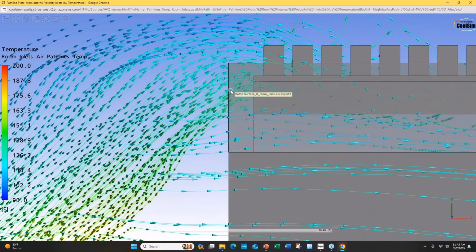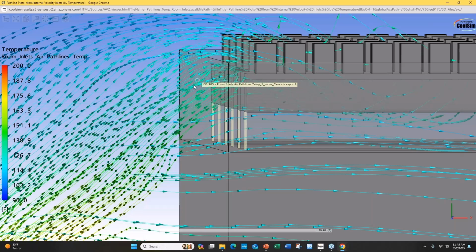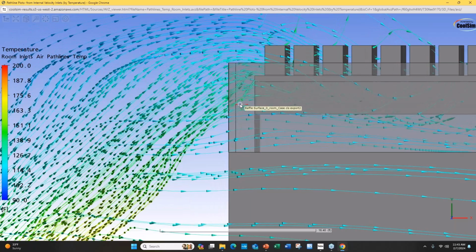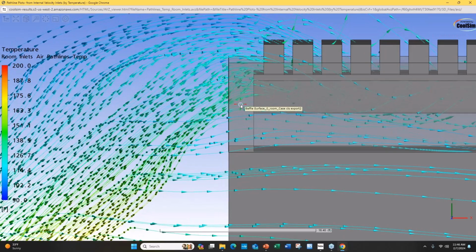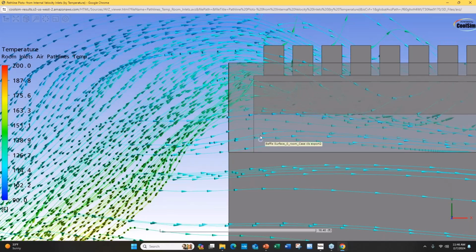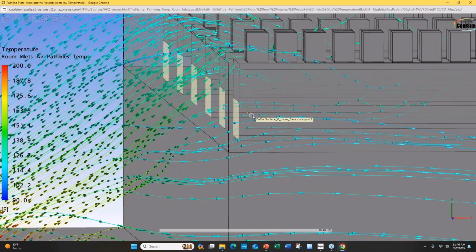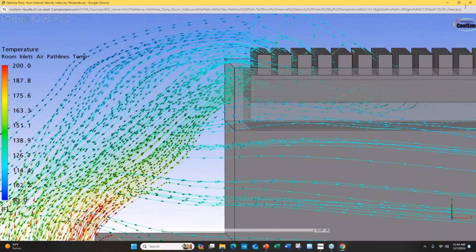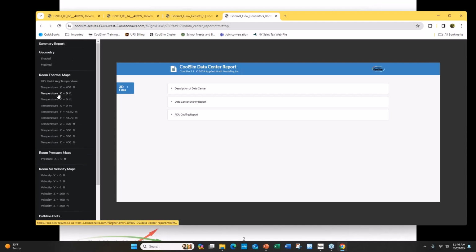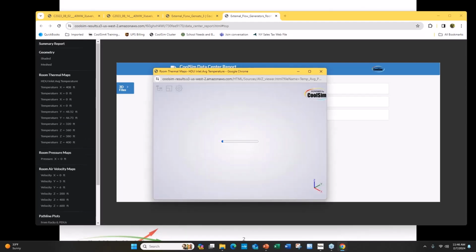So here we have percent area open set on that front screen. They usually are, and you can see it's still blowing through it. It's probably better than it was, but these screens tend to cause some of their own problems. As I mentioned, they create a low pressure inside them simply by the fact that you've got flow over the top of it, and when it goes to the other side, it creates a low pressure. But put a screen around it, and let's take a look and see if our HDU temperatures dropped. These are the condensers, the heat exchangers.